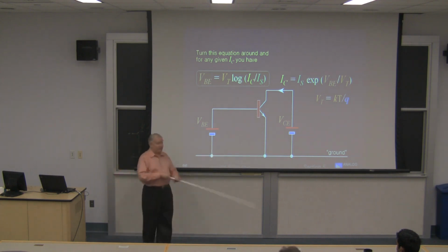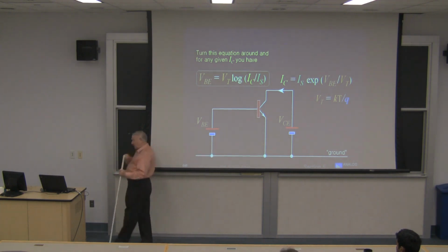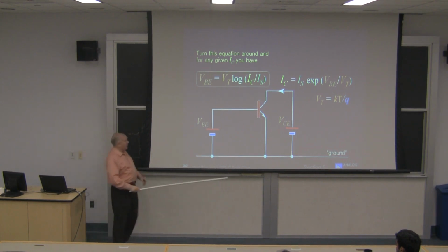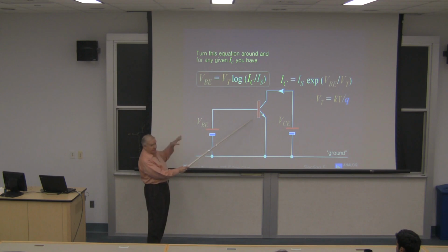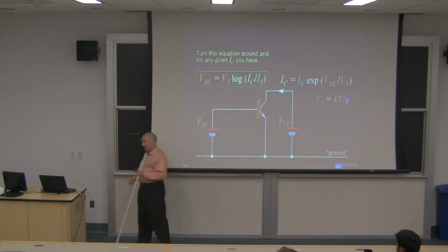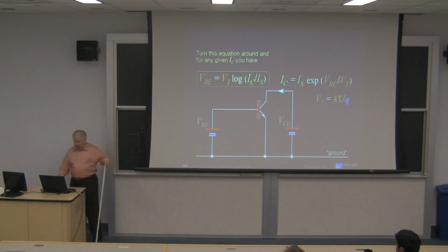And there are ways of dealing with that, some of which work and some of which are not so good. A simple example might be, in a more complicated circuit, to put transistors that have to match in the same pocket if you can. Of course, you can't always do that. So anyway, thermal consequences are very serious.